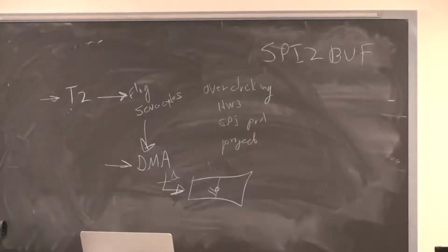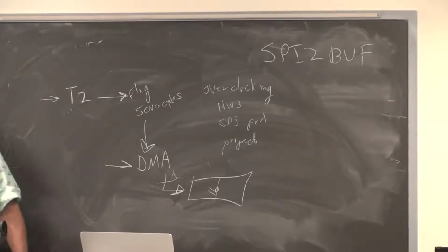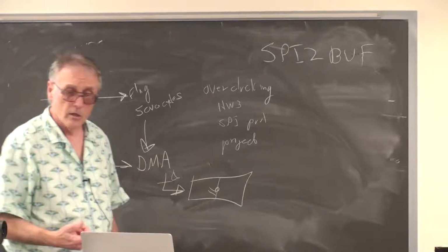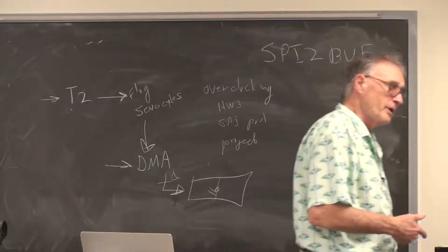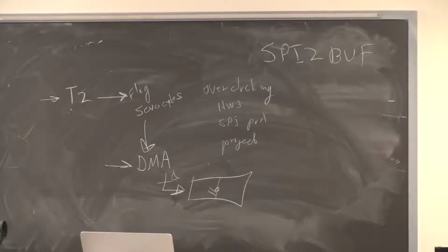The table size in this case is in bytes, and the units of this transfer is in bytes. For you, depends on what you're going to do, how you're going to open the channel, but probably this will be the sine table size times 2 because you need to send 2 bytes per entry.